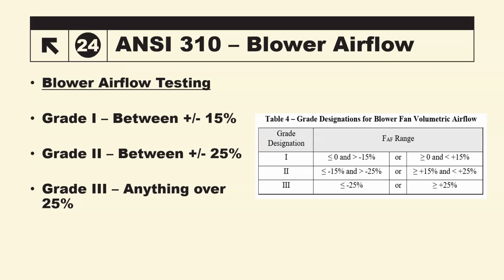But I mean, do you agree, Connor? That's kind of what we're looking at here, grading this system by giving it a report card, judging the full installation, including ducts that are installed. Yeah, I mean, this is where you get, obviously, total duct leakage is an aspect to it, and there's a reason why, if you're wondering why external static pressure is allowed to be used for the blower airflow from the OEM static pressure table. That's because you're able to see whether or not there's back pressure in the system from poor duct designs where it's been kinked and whatnot, and you get this increased back pressure against the coil. And so you're able to see essentially whether or not it's able to actually deliver that airflow, right?